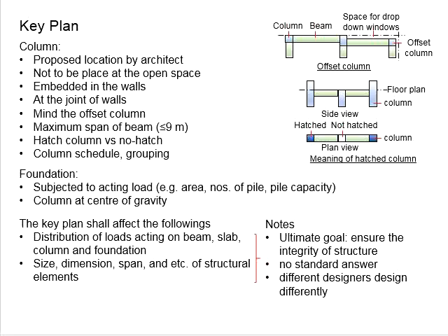You also want to design the structures to be as economical as possible. That means you might need to have good combinations of the beams, slabs and columns, and mind the effective spans, which can lead to a significant increase in the amount of reinforcement bar embedded in the structural elements.